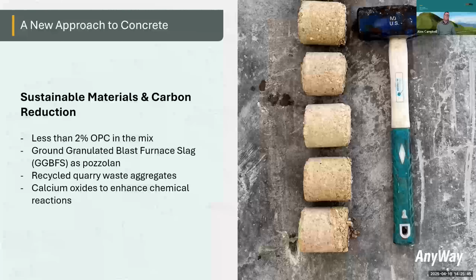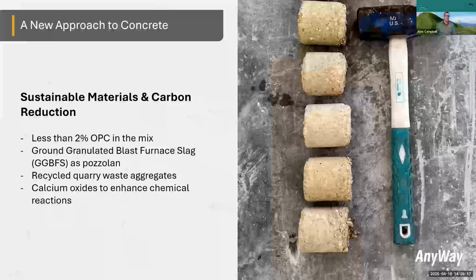The fineness modulus is too great, which isn't fantastic for hydraulic materials because it tends to lead towards cracking, and cracking in a road or a path is what we're trying to avoid. So it was important for us to take a look at that waste material and say, okay, how can we use this material to create something usable, therefore decreasing the footprint not only of the quarry, but also the footprint of the material that we are creating.